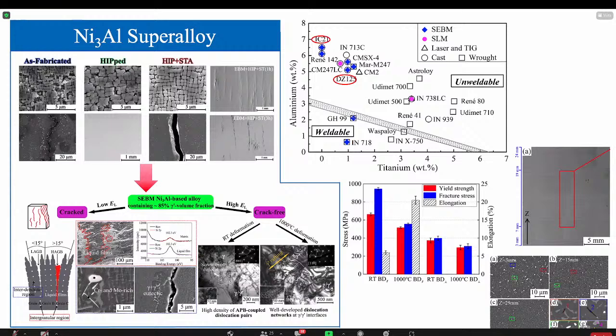And then we also understood recently that for such a crack to occur, it's basically due to the solution treating. When you give the sample the solution treating, you suddenly open up the crack. So what we learned from this failure is that you cannot rely on post-processing, such as hot isostatic pressing, to close these cracks. And this triggers the current work.